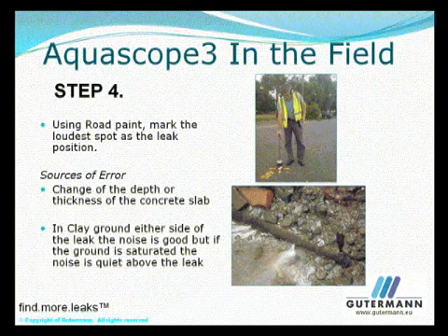Leaks in clay can often be displayed as twin peaks. It isn't two leaks, and the leak isn't at the loudest point. The ground is saturated at the leak position and a poor conductor of leak noise. The leak is often halfway between the two loudest points.